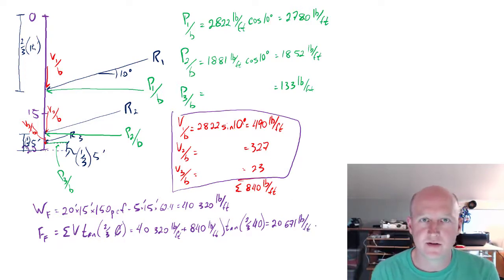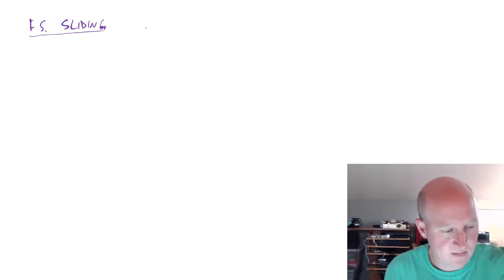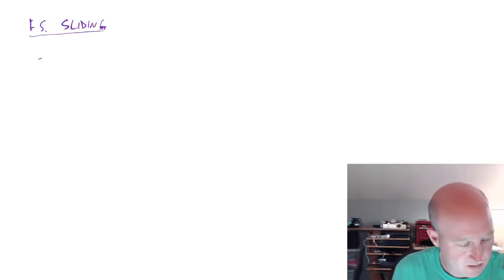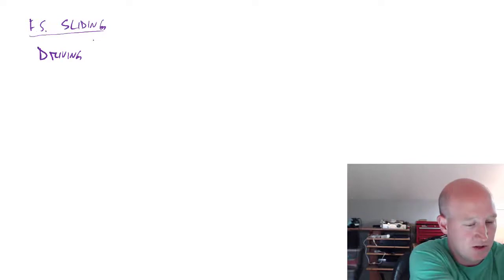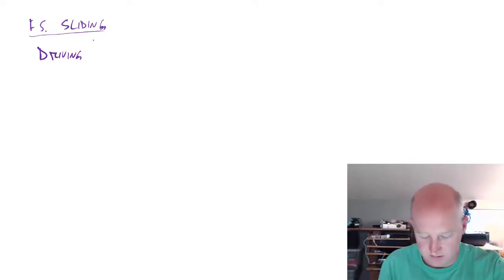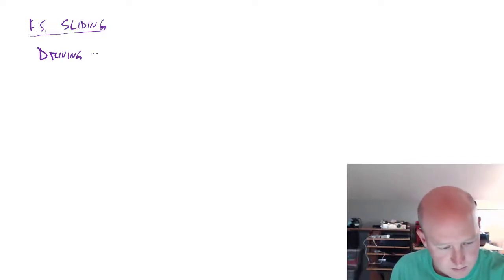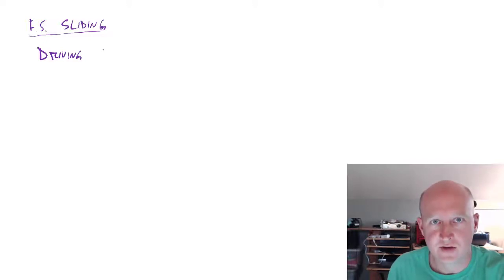Okay, so now we're ready to do our factor of safety for sliding. And so we need to know the driving forces. And that's going to be all of those soil forces that we added together. And that's just in the horizontal direction, remember.